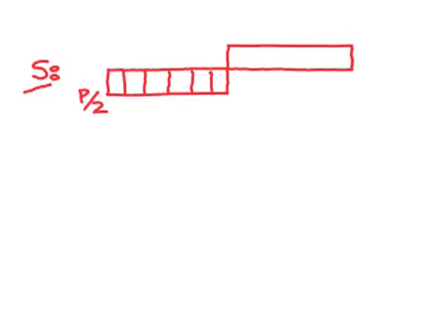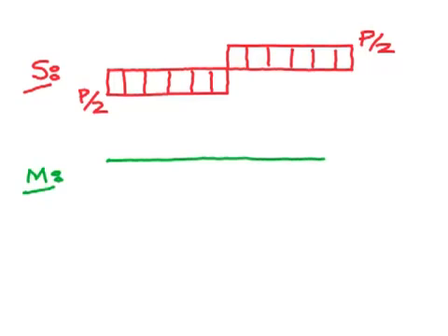For the bending moment diagram, in other words how the bending moment varies across the entire structure, the convention is to draw a positive bending moment on the tension side of any structure. So let's do that. We know that at the support on the left-hand side, the bending moment must be 0. Clearly, to the left of the beam, we have fresh air. We must have 0 bending moment at a simple support. The same goes for the right-hand support. So how does the bending moment vary?